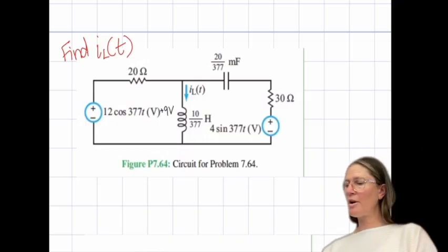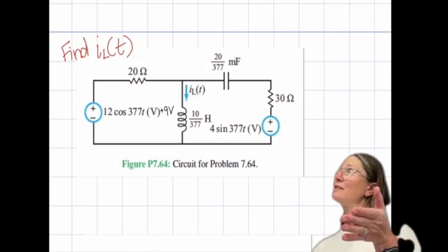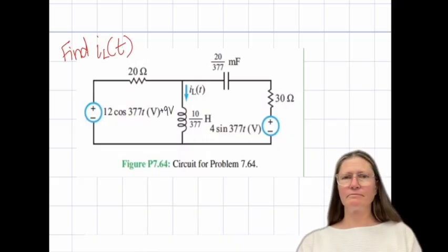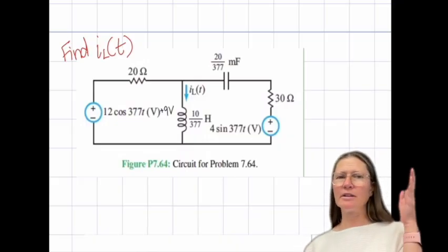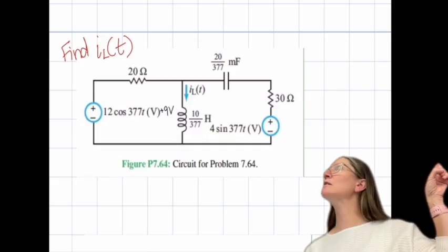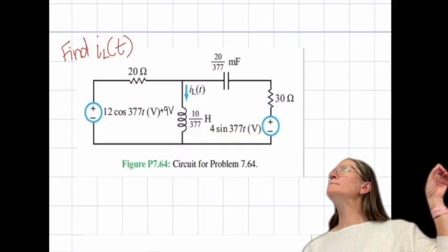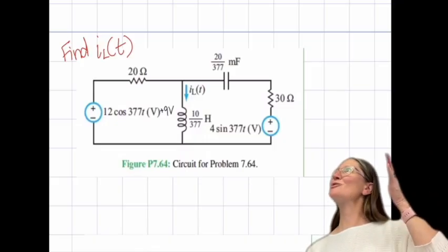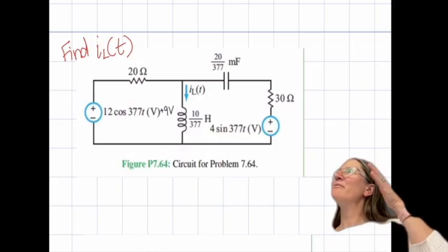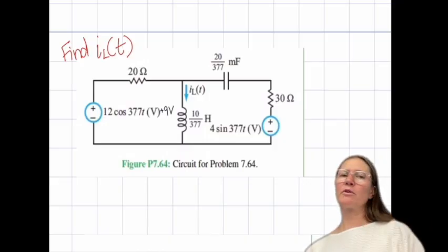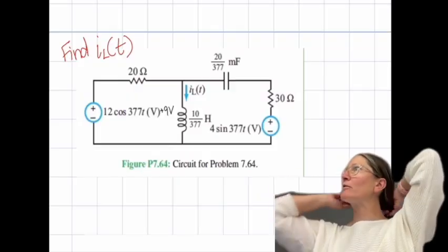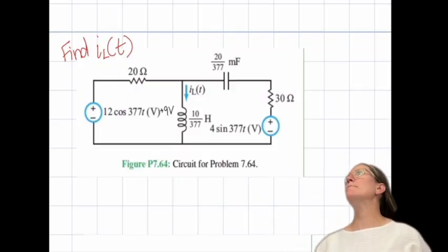Yeah, so you short out the AC, and then you leave just the DC as a source. Then you put a wire for the inductors because there's no frequency, and an open for the capacitor. So there will just be 9 divided by 20 for the DC part of it, as the superposition. Yep.